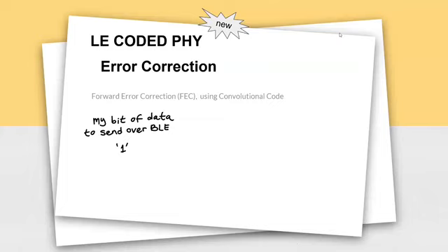But for now, what we want to understand is that each bit will be coded into more bits. Let's say I have the bit 1. This one will now be represented by 1 and 0. If I want to send the bit 1, it will first be coded into bits 1 and 0, and then transmit those bits. That way, even if an error occurs in a few of the transmitted bits, the receiver gets a partial data, and then it has a better probability to recover the mistransmission.